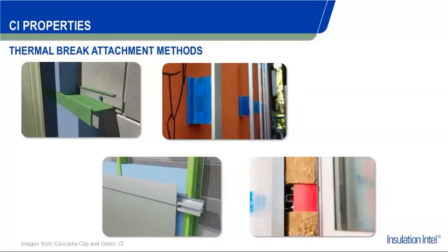And just by that separation, not only does it create an air gap to allow moisture to drain out and be taken away from the building through your flashing details, but it also separates the two structures so that we're not transmitting heat from the exterior to the interior, or cold air either way, depending on your climate.